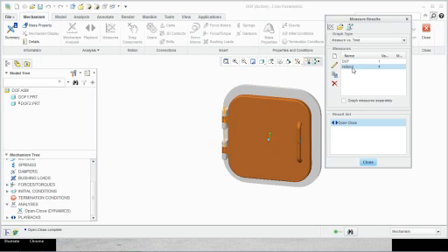Okay, so this will kind of give you problems in terms of your results at connection joint analysis, joint axis connection results could be wrong. I cannot trust them because my system has redundancies. So you have to make sure that your system doesn't have redundancies.